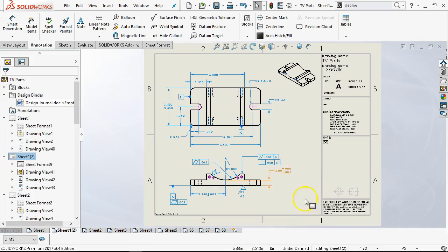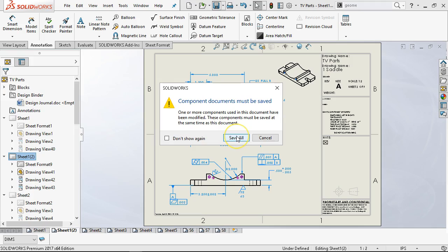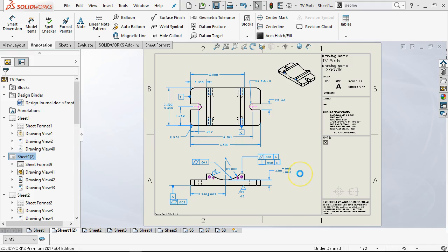All right, so once again, when I think of GD&T, it's supposed to make things easier, make things less complicated, and what ends up happening is if it's not applied correctly, it creates more confusion and leaves things open to interpretation. So try to pick your datums from things that are measurable, that you're establishing in the first few operations of creating the part. And then as you're building out through the frames, don't overdo it.